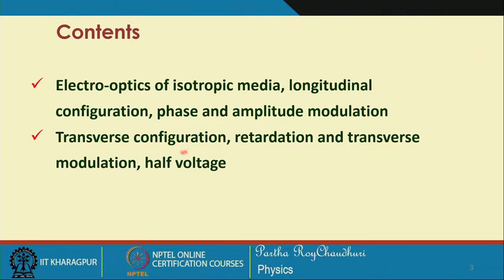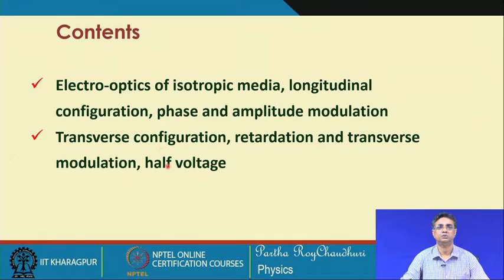After that we will consider the transverse configuration. In the transverse configuration we will see the retardation, phase retardation, and then the transverse modulation, and what is the half voltage required in that case to switch the modulator.